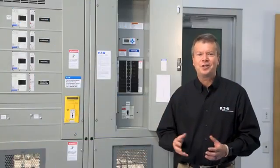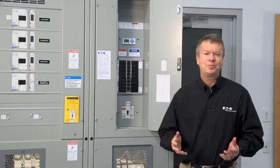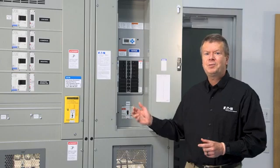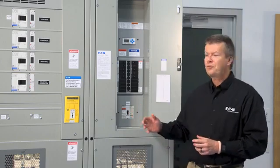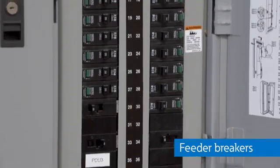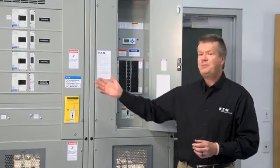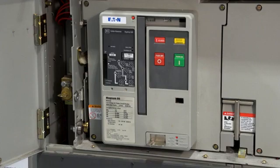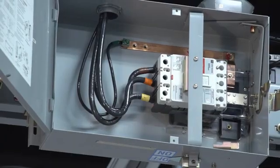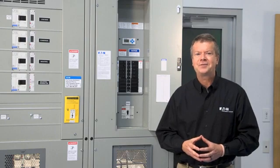So where are circuit breakers installed? Miniature circuit breakers are installed in residential load centers and commercial panel boards. Typically, molded case breakers are the main breakers for panel boards and maybe the feeder breakers in larger panel boards. Switchboards generally use MCCBs, and power breakers are used in low voltage and medium voltage switchgear. Busway uses molded case breakers in commercial and data center applications.